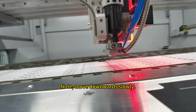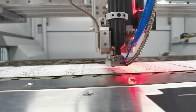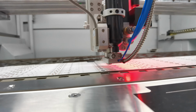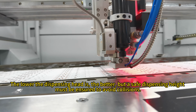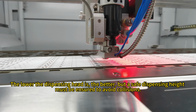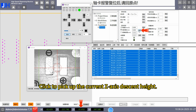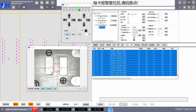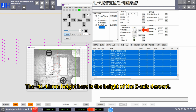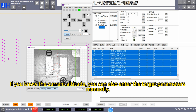Note, move downwards slowly. The lower the dispensing head is, the better, but a safe dispensing height must be ensured to avoid collisions. Click to pick up the current Z-axis descent height. The -41 point for 1 mm height here is the height of the Z-axis descent. If you know the current altitude, you can also enter the target parameters manually.